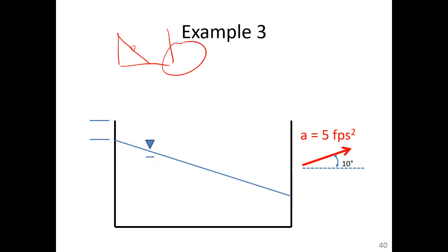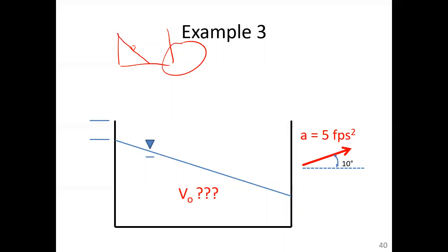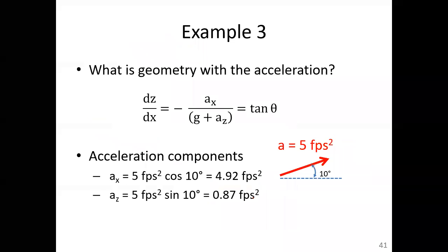What's the pressure distribution over here? Atmospheric, right? There's no fluid on it. So when you have an open container, you have to figure out whether or not you've lost fluid. We don't know if this acceleration field forced us to lose fluid or not.